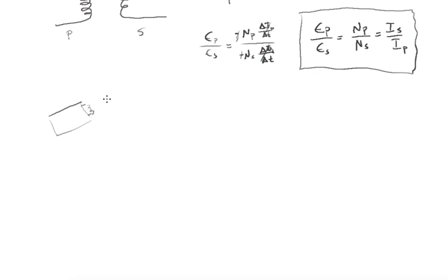So what you want is a really high voltage and a very low current. Well, that can come from something like this. So you can put a 9-volt battery in one of these things, right? Put a 9-volt battery here, and then what you do is you ramp that voltage up from 9 volts to your primary, and you use a step-up transformer, right? And you ramp that 9 volts up to something like, say, 30,000 volts. And so if you look at this, you end up with a very small primary and a huge secondary voltage, and look at what that does to your current. That's a small number over a big number. That means you're going to have a very small secondary current.